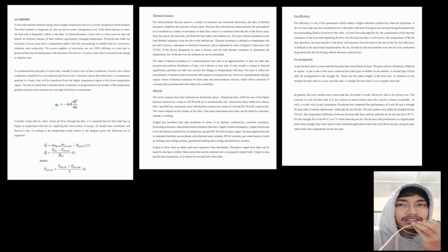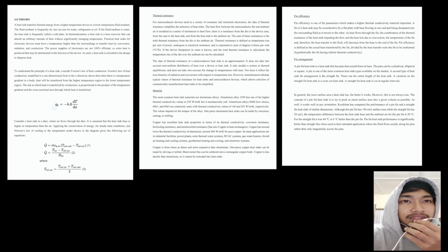Okay, Assalamualaikum. For the theory of this project, firstly, a heat sink transfers thermal energy from a higher temperature device to a lower temperature fluid medium. The fluid medium is frequently air but can also be water, refrigerant, or oil. If the fluid medium is water, the heat sink is frequently called a cold plate. In thermodynamics, a heat sink is a heat reservoir that can absorb an arbitrary amount of heat without significantly changing temperature.